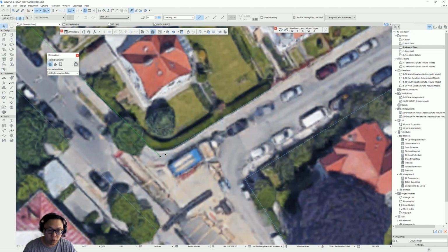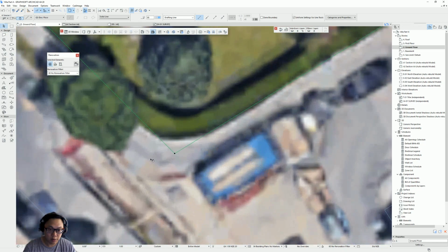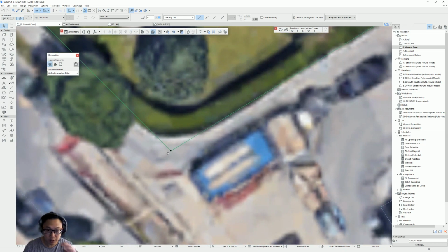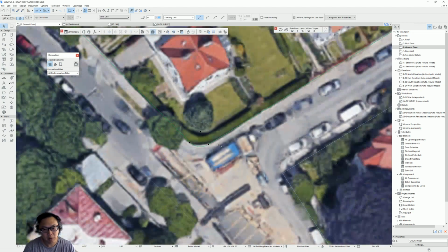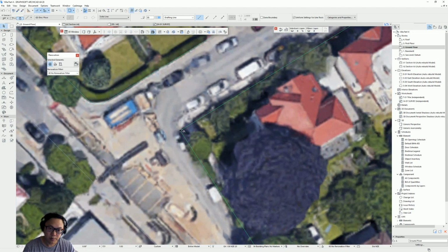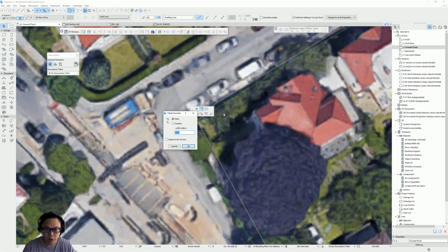So now you can round the corners: select the two lines and make sure that they meet at a single point, and then you go over to that point, and there's this little fillet. So you go here, radius, that's up to you, let's say 3000. That's about right. So I'm just going to do the same here. Select the two lines, then the node where they intersect, click it and go into the fillet, press 3000.